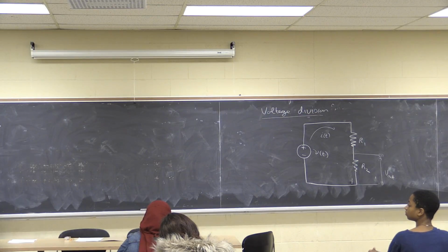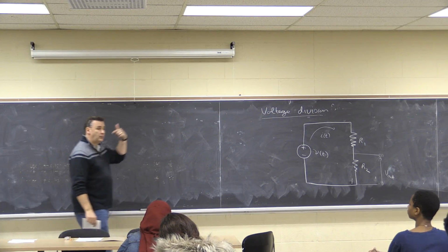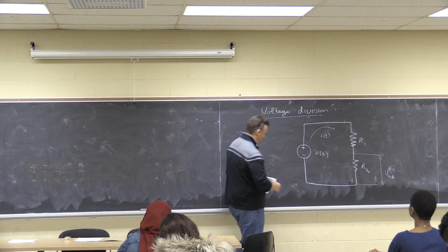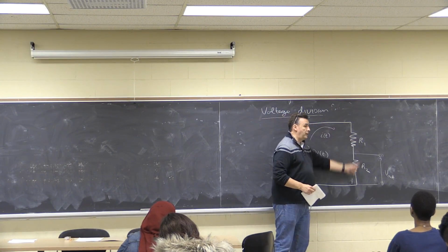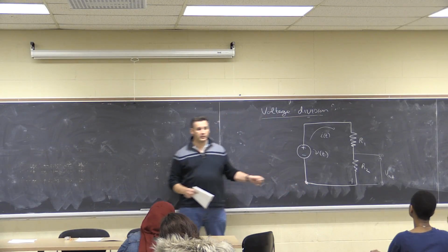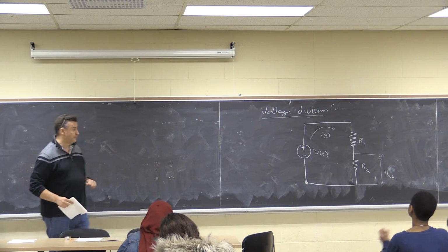So this one I'm going to apply Kirchhoff's voltage law, because I've got a single loop. If I walk around that loop, if I start at a point down here and walk all the way around the loop, I'm going to be back at the same voltage. That's what his voltage law says.